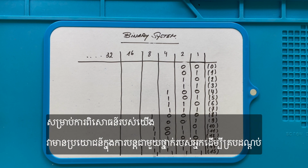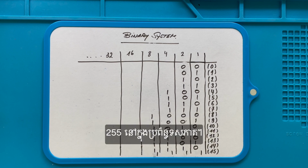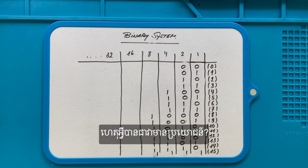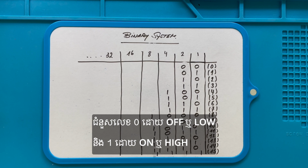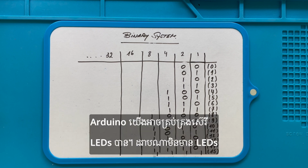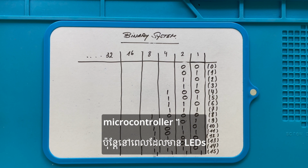For our experiment, it is useful to continue with your class to cover 8 digits and calculate with them that 11111111 equals 255 in the decimal system. Why is this useful? Replace 0 with off or low and 1 with on or high, and you can see that by sending a series of zeros and ones to a digital pin on the Arduino, we can control a series of LEDs. As long as there are not too many LEDs, we are able to connect them to the digital pins of the microcontroller.